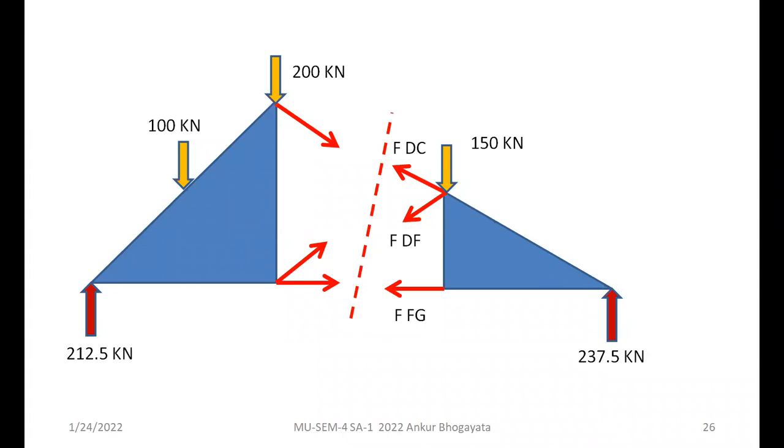Now, once you have cut the sections, I mean the members, convert them into forces, as you already know, right? Every time we used to take the left hand side. So this time, let's take the right hand side, just for the sake of change. So I have shown all the forces on the right hand side section, and I'm going to consider equilibrium conditions for the right hand side this time.